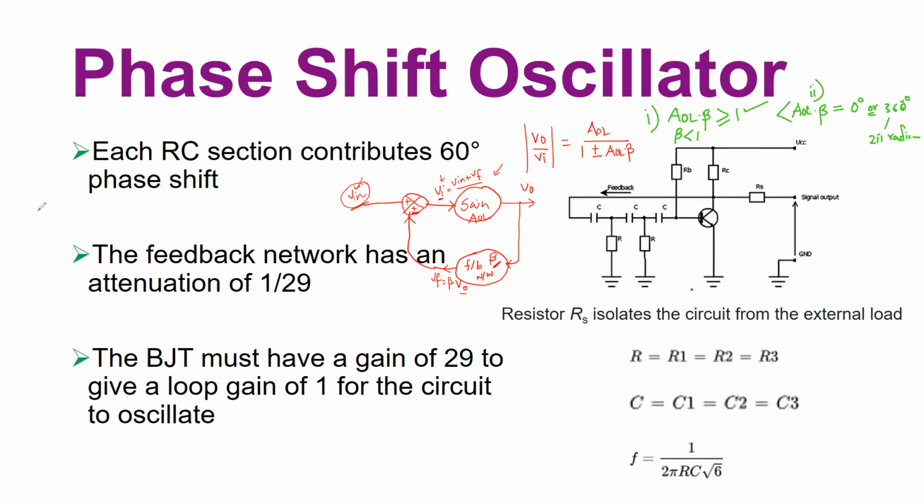So what happens for the feedback oscillator, when you have a positive feedback, you actually disconnect this external input source, and the only circuit that you have is right here. Let me draw here. So the only circuit you will have here is a gain block, and then you have an output, and then you have this feedback network, of course, and the output is connected to the feedback network, and you have removed the external input.